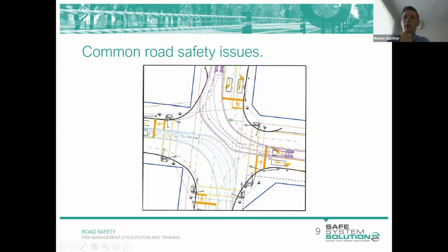When we look to the purple diagram, we can see that the swept path has been manipulated, with several turns within the single right turn manoeuvre in order to complete the movement. Now, that's not typically standard, nor is it safe. And it doesn't meet the requirements of the guidelines. So for it to meet the requirements of the guideline, it's got to look very similar to this, be very consistent and intuitive to what would actually occur on site.